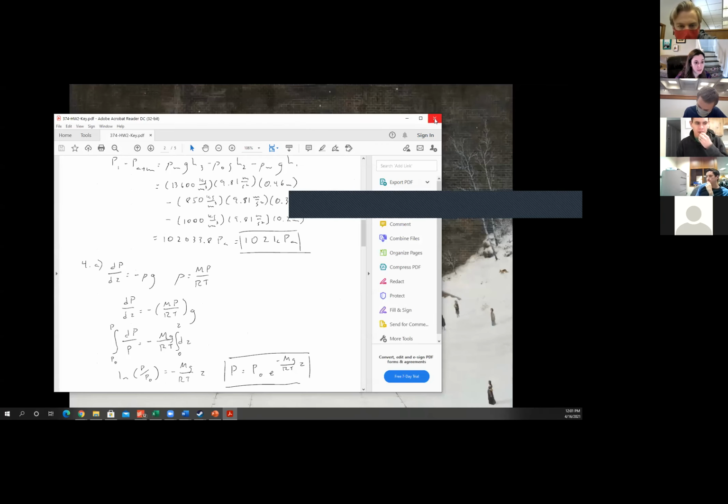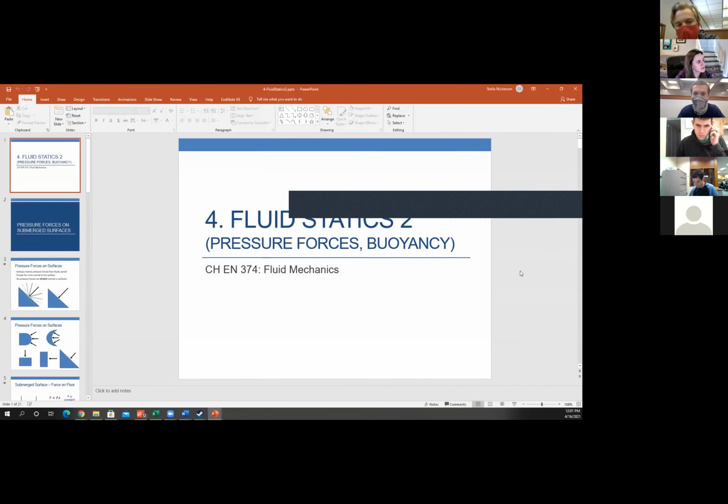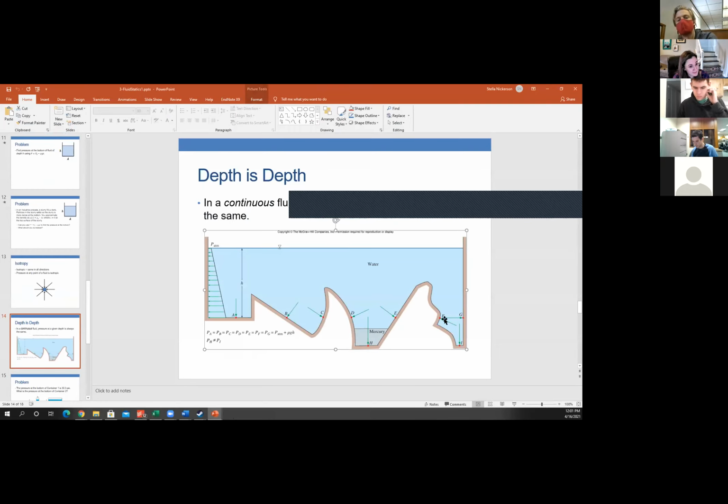All right, so then we talked about pressure forces. That is what we talked about next. There's a few other things, like pressure at the same depth in a fluid is always going to be the same. That was something we learned that's kind of a good thing to know. All right, pressure forces. Actually, let's go back there. Okay, just a couple other things to know about pressure. In the same fluid, if you're at the same depth, pressure is always going to be the same, because that's all pressure depends on, right? P is equal to P naught plus rho gh. So pressure is always the same everywhere at the same height in the same fluid.